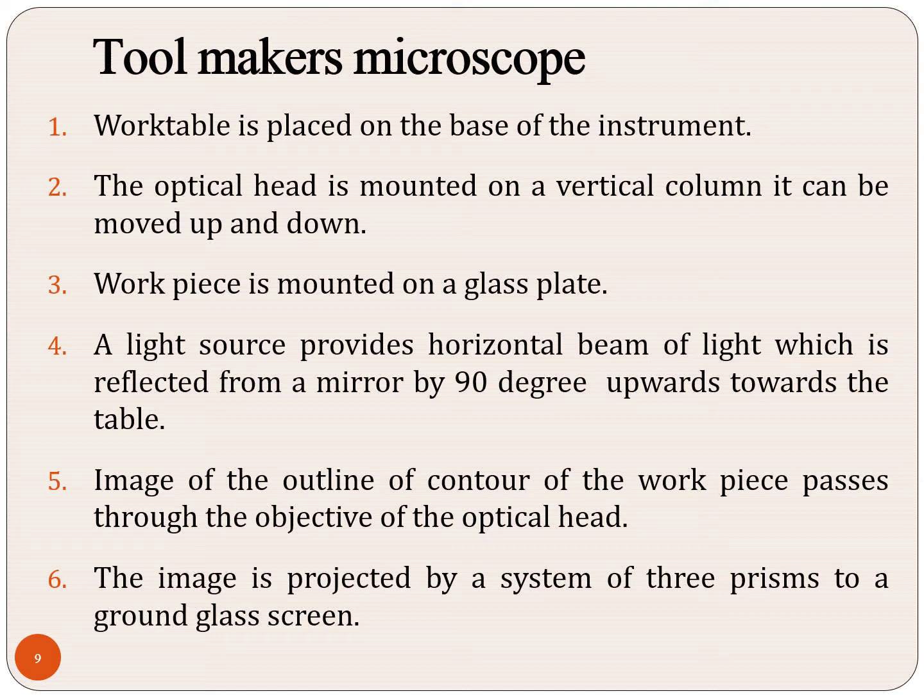Workpiece is placed on the base of the instrument. The optical head is mounted on a vertical column. It can be moved up and down. Likewise, like a microscope, workpiece is mounted on a glass plate. A light source provides a horizontal beam of light, which is reflected from a mirror by 90 degrees upwards towards the table. So now look at this